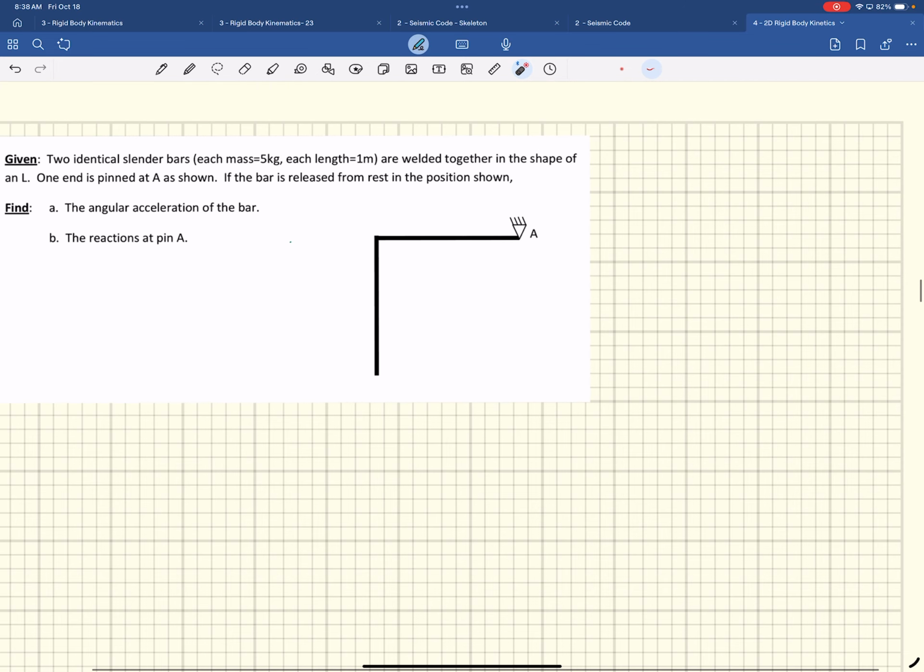Like when we do this one, there's this guy and then there's this guy. And again, remember the axes are coming out like this. So if I was trying to figure the moment of inertia about this axis right here, the distance that I care about is the D that you would use for this problem. If you started over the weekend, be careful of that, because you picture the axes coming out, and it's the distance between the axes. There's one where we go about this end here, and you just have to make sure you know that that's coming out of the board and the D that you care about is that D right there.